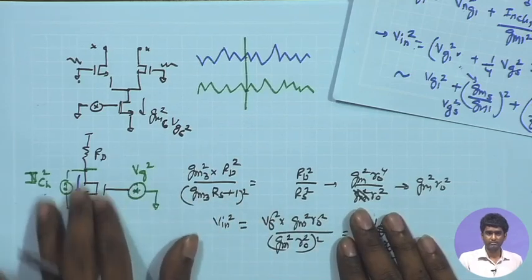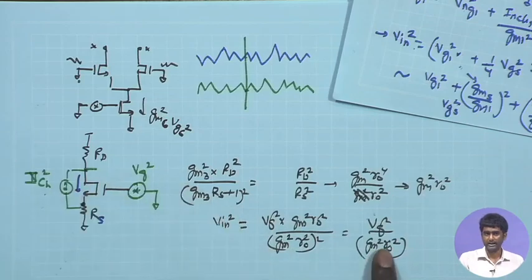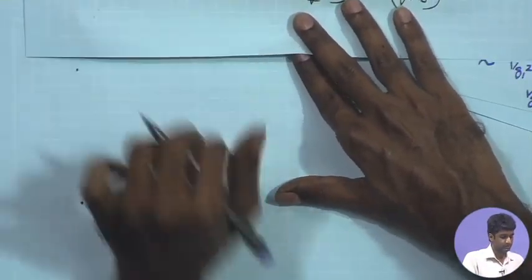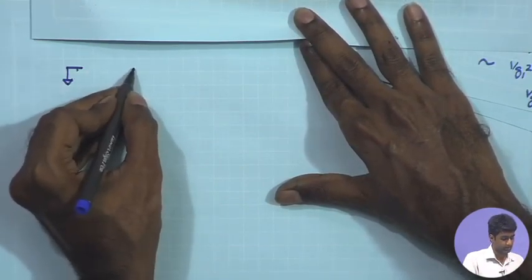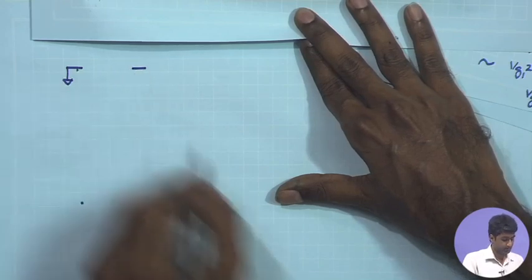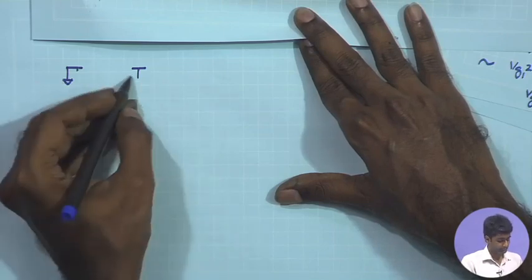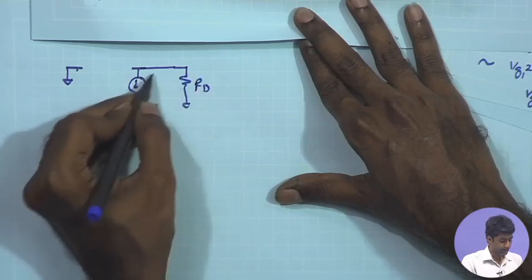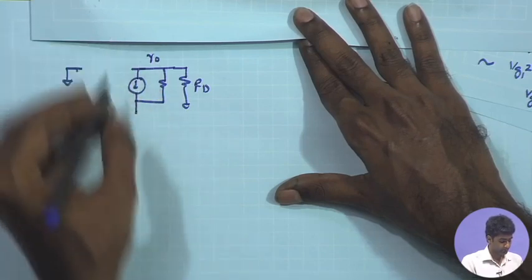And analytically also, in this circuit, we can try to solve the KCL and figure out what the expression for I channel is. We can do that very quickly. If I look at this model, assume the VG is 0. So the MOSFET gate is 0. Gate potential is AC ground, and therefore I can look at the GM VGS term. You have the RD, which is between the drain and AC ground, and you have the RO, and also you have the RS over here.